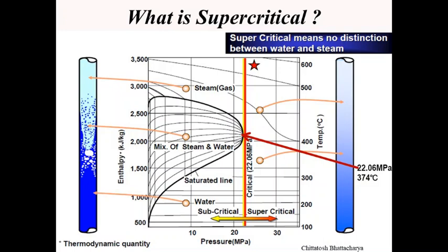This increased rate of heat transfer actually depends on the circulation ratio, and the more heat we infuse within the steam and water mixture, the more chance there is of an increase in tube metal temperature. So we have to see that we can continue the addition of latent heat within the domain of nucleate boiling.